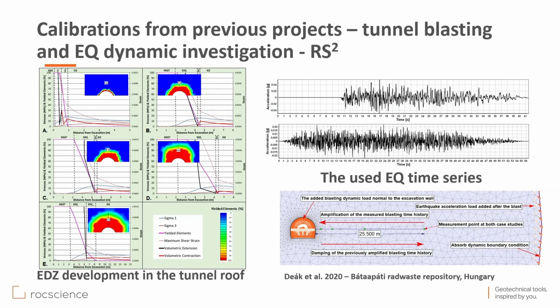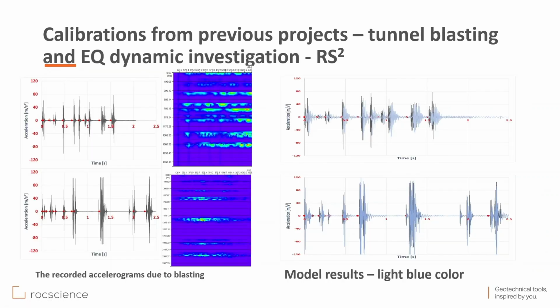And what is important is that, of course, during the measurement, the conventional tunnel work was interrupted in both tunnels, and the ventilation system was turned off. So we could consider the tunnels seismically silent. So here are the 2 points, and let's see how the model looks in reality. We can see that during the blasting we had very high frequencies. Here you can see the spectrograms, and here you can see the final results.